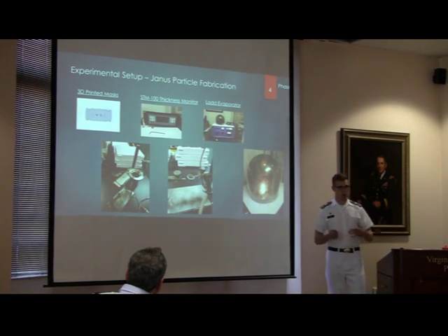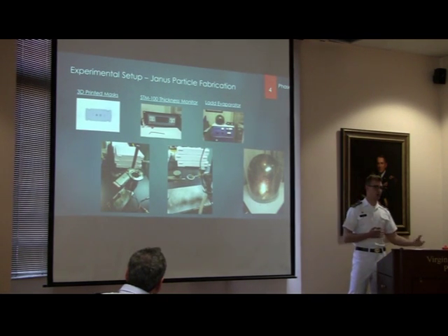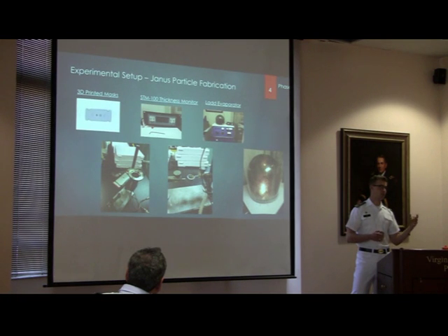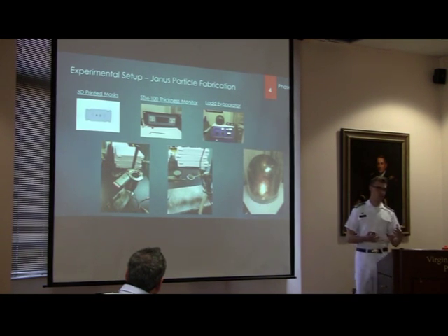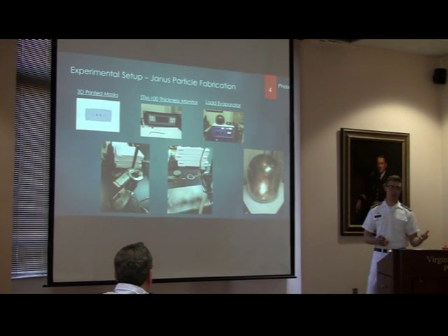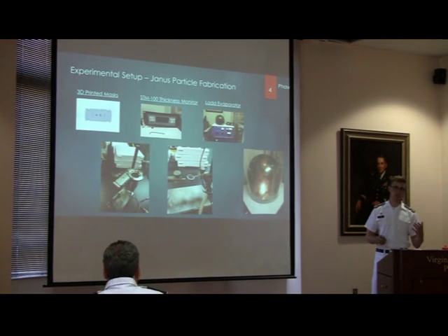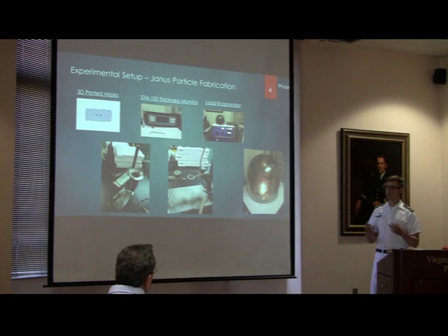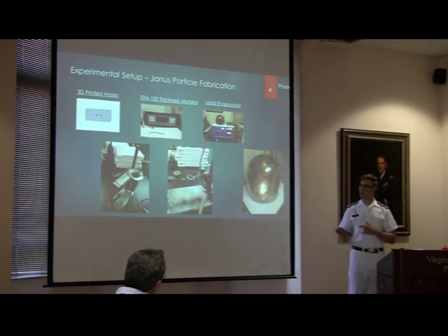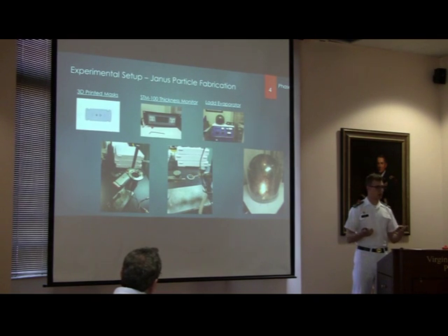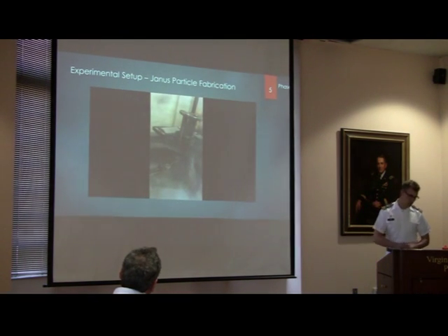The machine would pump it to 10 to the -6 torr, which is extremely low pressure. For those of you familiar with physical properties of materials or some sort of chemistry, that actually changes the melting point. It brings the melting point down, which meant we didn't have to get this nickel quite as hot to evaporate. So that's what I'll show you here.